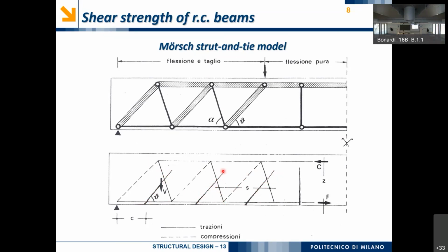resisting actions. So we can see that there is a superior part, una briglia superiore in Italian, a chord that is purely under compression. This chord is associated with pure concrete. Whereas there is also an inferior, a bottom chord, una briglia inferiore, that is undergoing tensile force. This chord is just associated with the longitudinal reinforcement of the bar, that was not put there for the shear behavior, but for the bending behavior. But it still allows the cross-section, the structure, to balance these failure mechanisms.